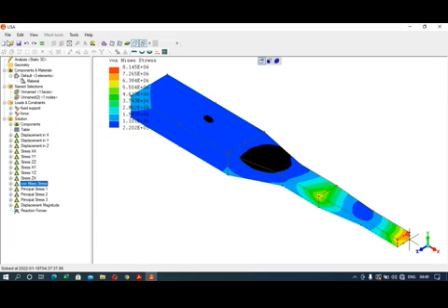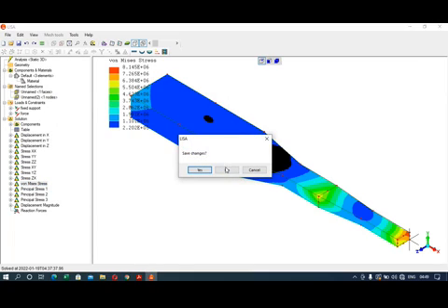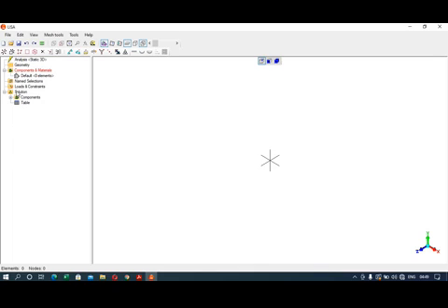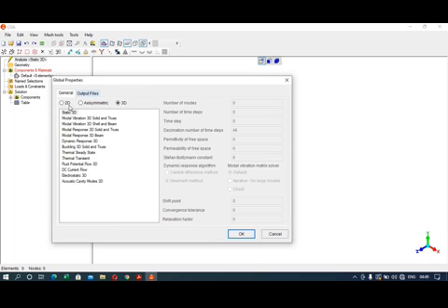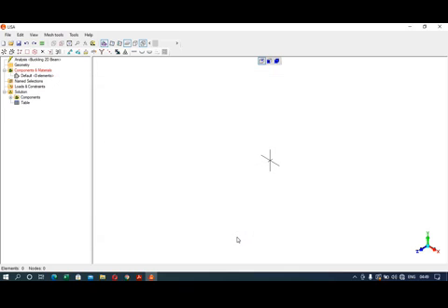So I will create a new analysis. First analysis, static 3D, right click on it, click on edit, select the 2D, then buckling of 2D beam. The number of modes I am going to select here is 3 and the shift point non-zero value which is 0.2. Click on OK.